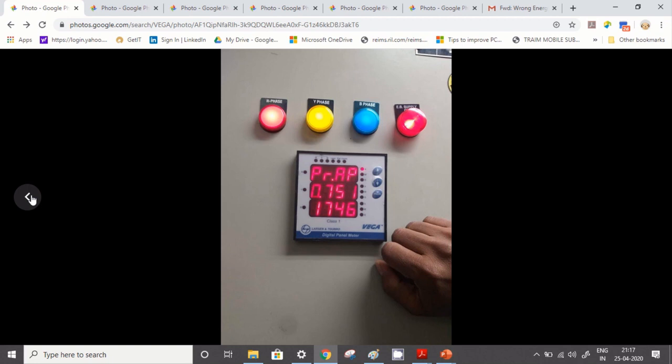Once you do all this wiring and all the parameter settings, and if everything is okay and your communication port is working fine, in that condition you will get the values in your SMPS controller first of all, and after that in your remote monitoring system. So first check your connection, do the right settings, parameters and configuration, and after that hard reset the SMPS controller once. After the hard reset, if your communication fail alarm disappears, that means your communication is okay.